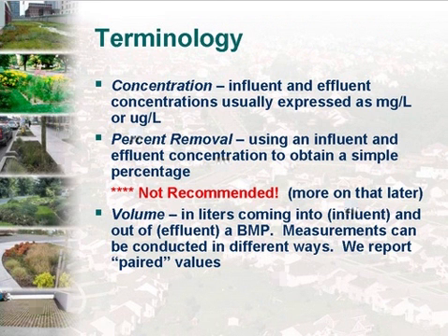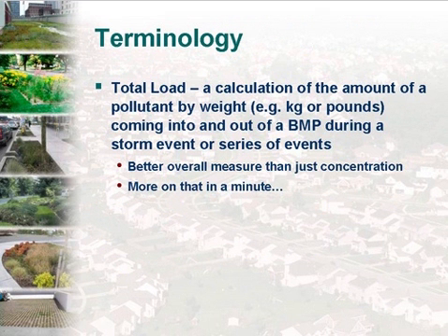Volume, of course, we're measuring here in liters, and we want to compare the influent to the effluent. And in the new class of BMPs that everybody's talking about now, whether you use the words low-impact development or better site design or green infrastructure, whichever term you like best, those are all pointing at a common idea about infiltrating stormwater, trying to deal with it in a more natural way. And so volume reduction becomes a very important piece in this whole scheme that we're talking about.